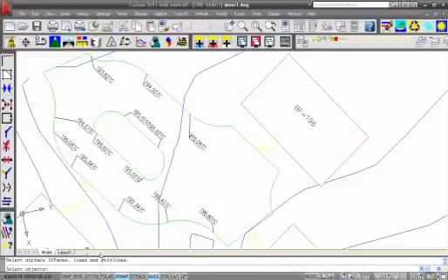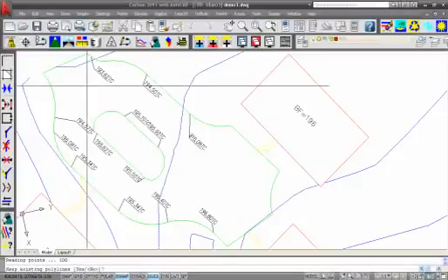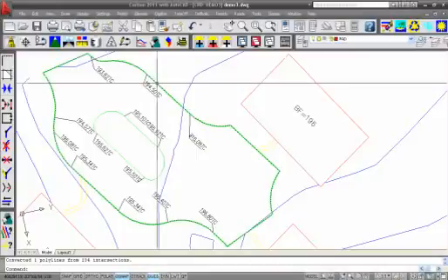And select the 3D faces, lines, or polylines to elevate it by. So I could type in all and select all the contours. I'm just going to click on the 3 that are close by. So I have 3 contour lines selected. I'm going to hit enter. Keep existing polyline, I'm going to say no. And change the layer, no, I don't need to. It says converted 1 polyline.